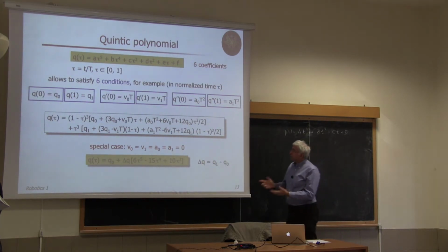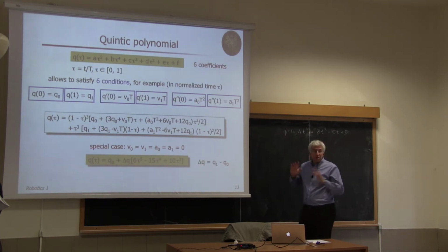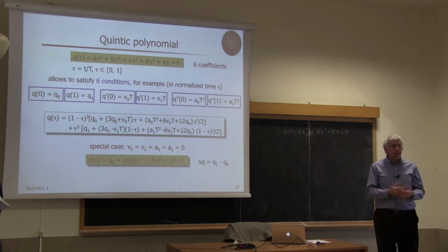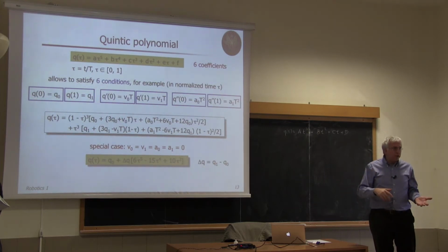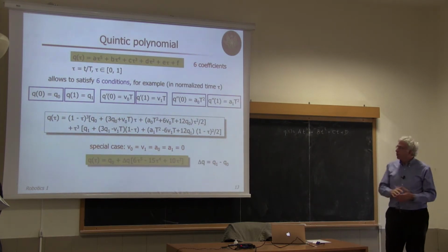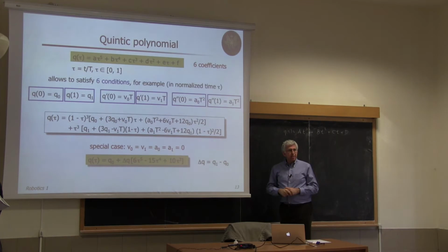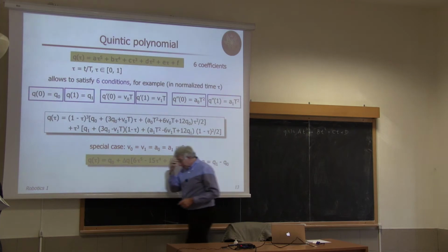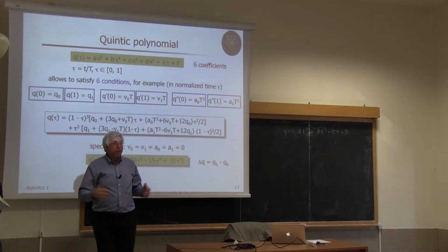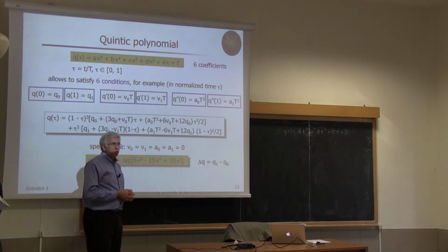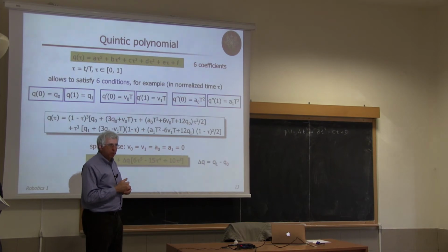So when you impose this for general boundary conditions, so this is not a rest-to-rest motion. You can start with non-zero velocity and reach the final point with 0 velocity or vice versa, or both velocities are different from 0. The acceleration may be 0 or not, one or the other or both, and so on. So here you find a solution already written in this special form. If you happened to find this in some numerical analysis course, this is a form which is also called Lagrange or Lagrange-like form of polynomial.